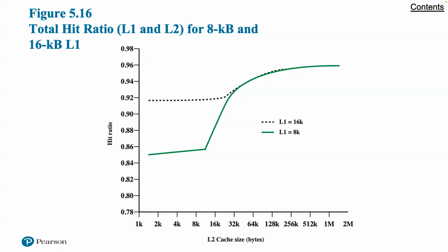With increasing availability of on-chip area available for cache, most contemporary microprocessors have moved the L2 cache onto the processor chip and added an L3 cache. Originally, the L3 cache was accessible over the external bus. More recently, most microprocessors have incorporated an on-chip L3 cache. In either case, there appear to be performance advantages to adding the third level of caching. Furthermore, large systems such as the IBM mainframe z Enterprise system now incorporate 3 on-chip cache levels and a 4th level of caching shared across the multiple chips.